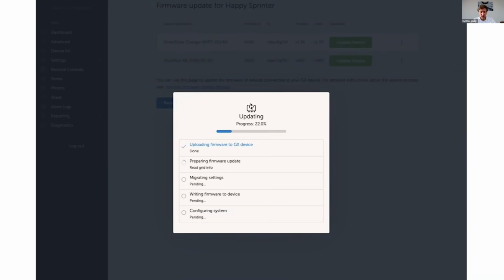And while on this topic, it's the same with Victron Connect. If you use the Victron Connect app on your phone, you don't need internet to do a firmware update, because the Victron Connect app contains all the firmware files for all Victron products. You can try this easily by switching on airplane mode, or by somehow blocking the internet connection on your phone.